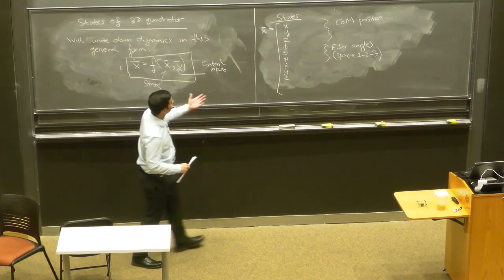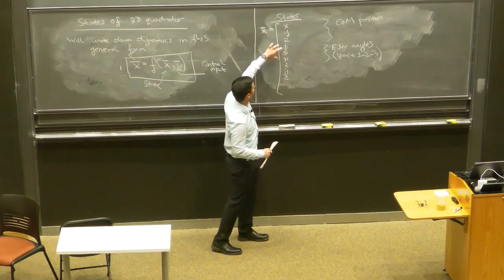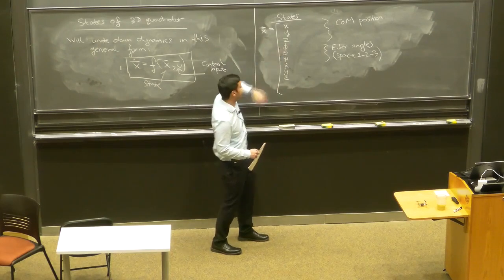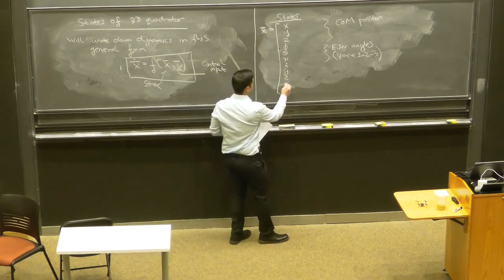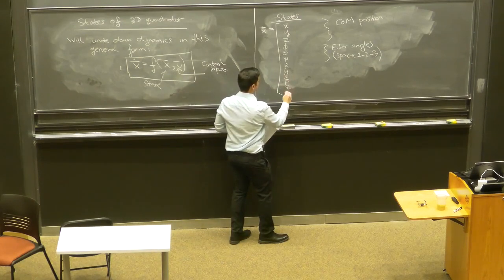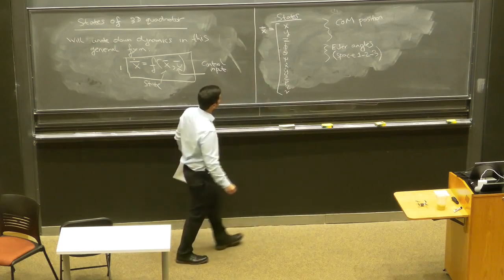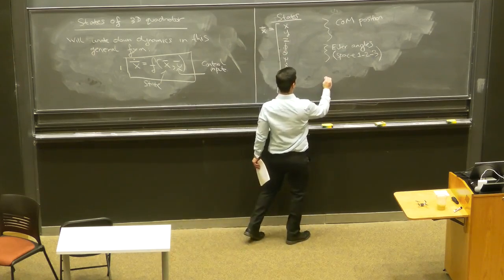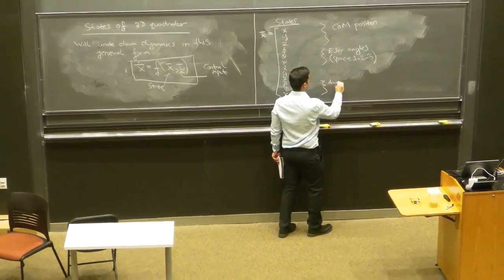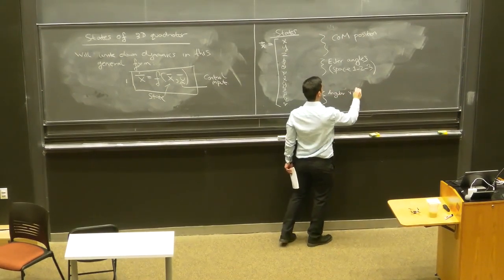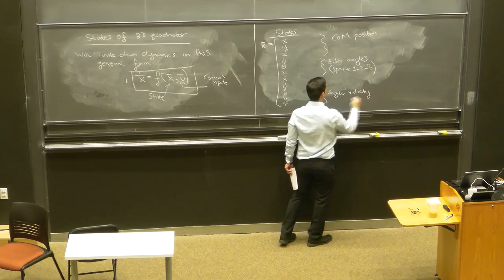And then finally, there's a kind of choice here. We could go with phi dot, theta dot, psi dot, the time derivatives of the Euler angles. It turns out it's slightly more convenient to use some other variables, p, q, r, which are going to be the angular velocity vector.